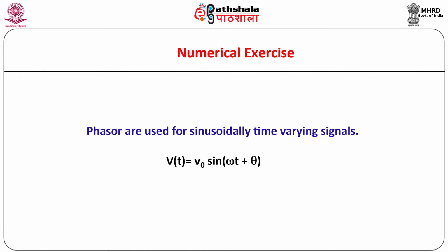According to one of the two main conventions followed while solving electrical circuit problems using phasor notation, V = V0∠θ is taken to represent the sinusoidal voltage, v(t) = V0 sin(ωt + θ), where ω is the angular frequency of the signal. It should be noted that phasors are simply complex numbers having magnitude and phase.